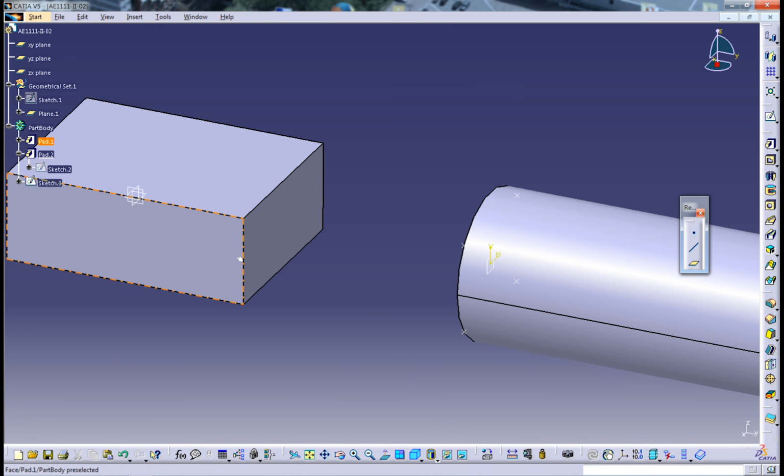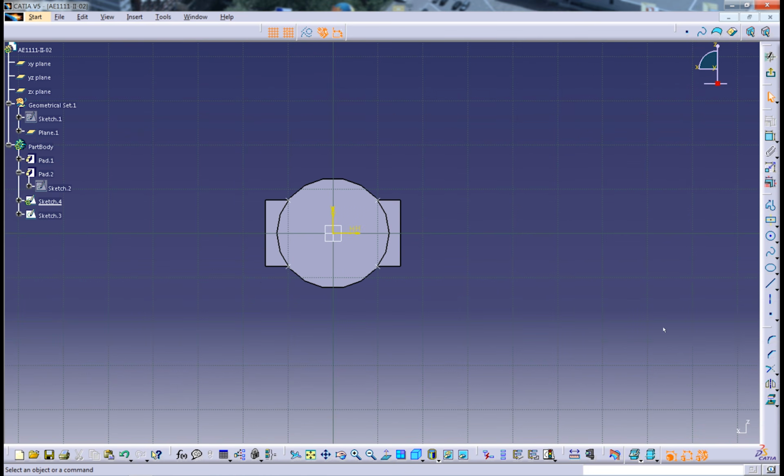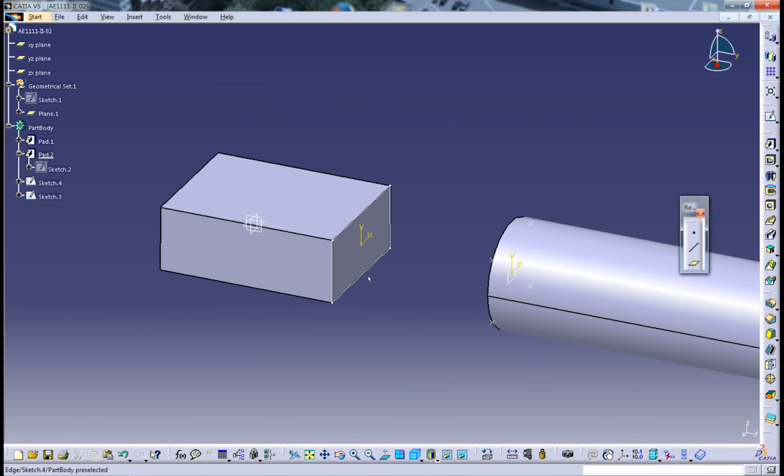Before we connect them, we have to do one small step. Select the plane, this one here, and select sketch. Now we use from our right side our tool project 3D element. Select it and click on the face again where we make it sketch. And then we see we have a yellow-orange outline. And this indicates we made 3D element. So the outline of our rectangle we projected on our sketch. So we can leave the sketch. And here you can see this outline. And this one we need to make the connection between our circular pad and our little block here.